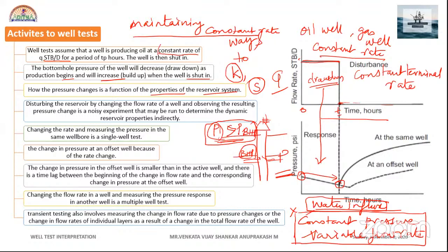Now what happens when you shut off the well, or shut in the well? Initially it is continuously producing to the surface. All of a sudden you close the well at the surface. You'll observe that until the fluid fills this region, it will show some response.